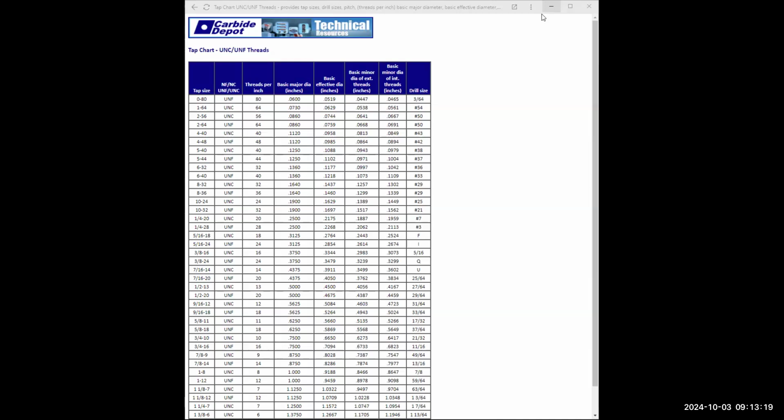And then we're going to type in DP 0.75. Enter again. What does that mean? That looks a little bit different than our drawing. Look, if I double click on this, when you make your diameter symbol, it's percent C. That's how you make your diameter, so percent C.